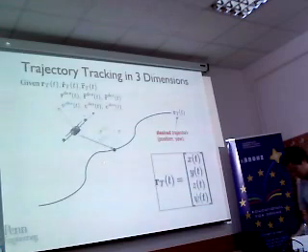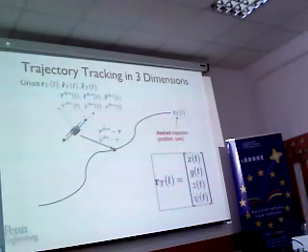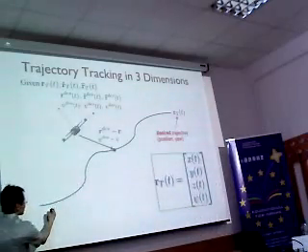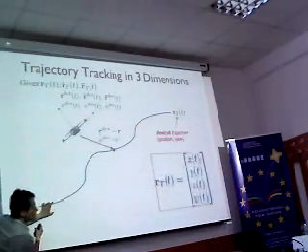As before, we'll be interested in the difference between the desired position and the actual position. But now, we're also interested in the difference between the desired yaw angle and the actual yaw angle. So you can see that we have two parameters to be considered. This is the desired, it means that it will follow this trajectory, right? And this is the current value. So, for example, at this time, the current position will be here, not here, right? So it can calculate this is the error.